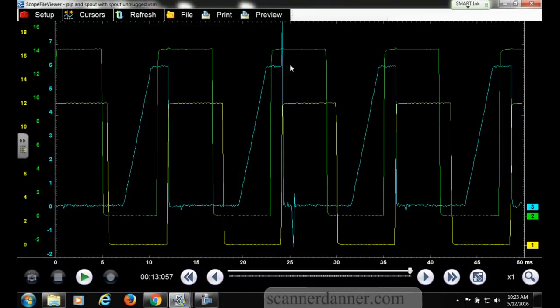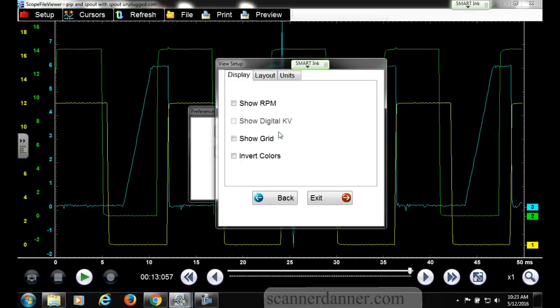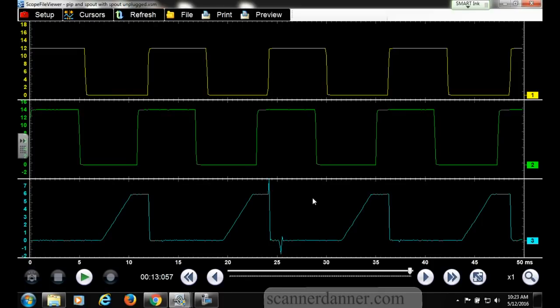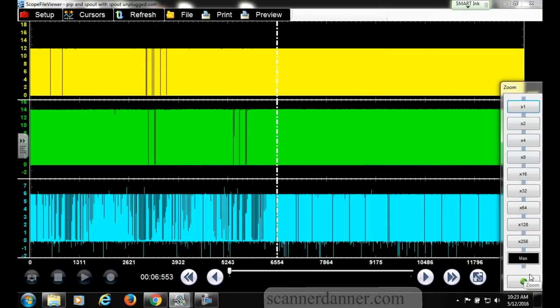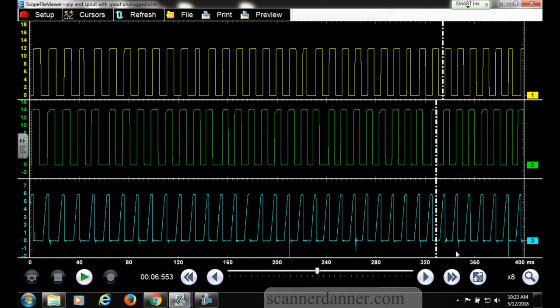I had you guys check the coil signals, and if I turn this other stuff off, just look at the blue trace for me for a minute. What I had you guys do, remember when it was misfiring and I said, can you look at the coil firing events for me? Because I wanted to know what it looked like. What do you think was on my mind whenever I told you guys to do that? This system, this distributor, I've been here before, got my ass kicked by this thing before. You understand now why I had you do the coil events.